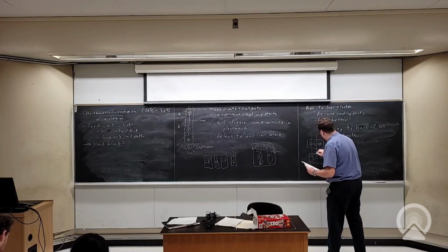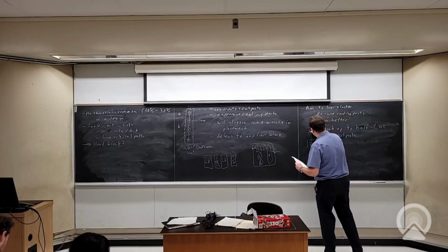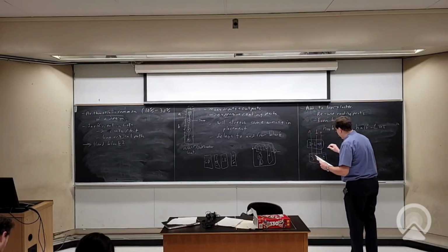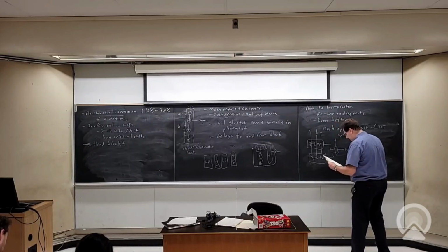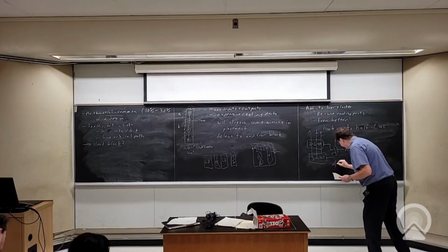There are 3 inputs that go to both those, so A, B, and C. And then the outputs of those 2 go to another mux with the last input D, and you get your out. Okay, so that's my 4 LUT.